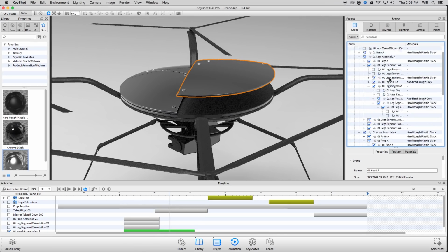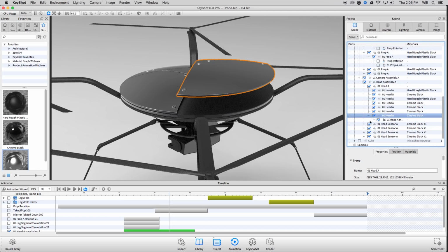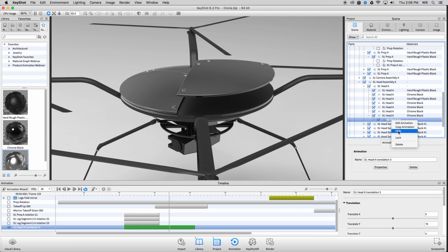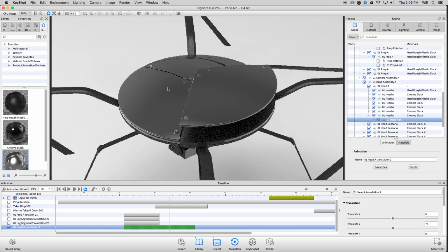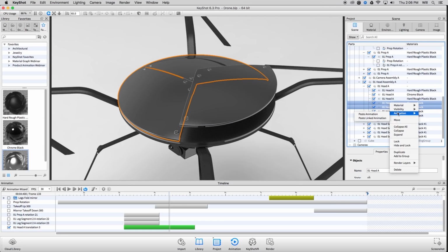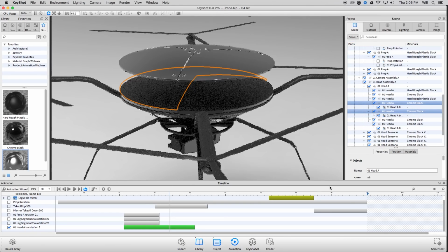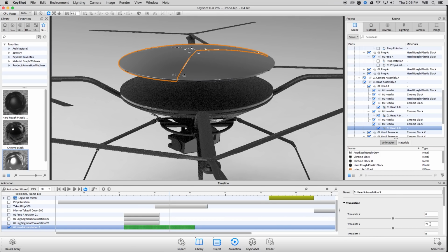And what we'll want to do then is, in the scene tree, find that animation. So what I always like to do is click on the part so I can quickly find it in the scene tree. I find the animation, copy that, and make sure I apply it to the next couple of pieces. Then with a right click in the animation, paste linked. So those are going to move up, and I can say 70 is not enough, maybe 150.